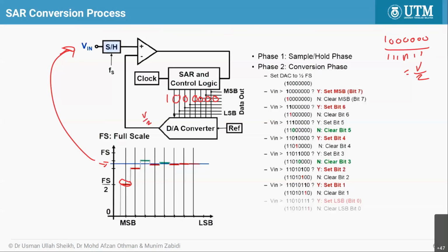Okay, you want okay, yeah? So why do we need to divide by the 1111111? Because that's the way it works. You test from the MSB first. You want to check the MSB. Right now we want to convert this unknown value to a certain value finally, after the conversion is finished. But to do that, you have to convert using binary search. This is binary search. Okay, you have a lot of voltage, you have 0 to 255.